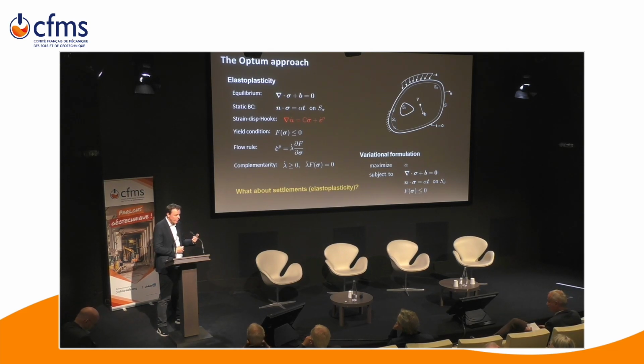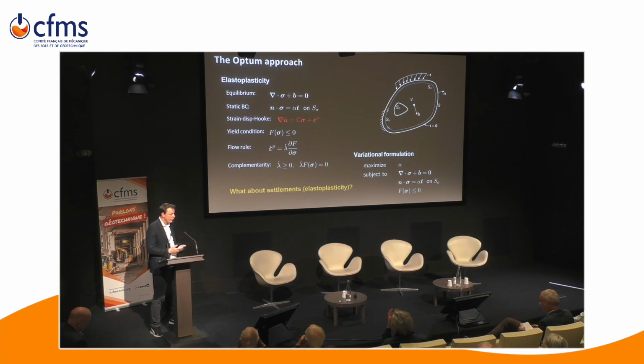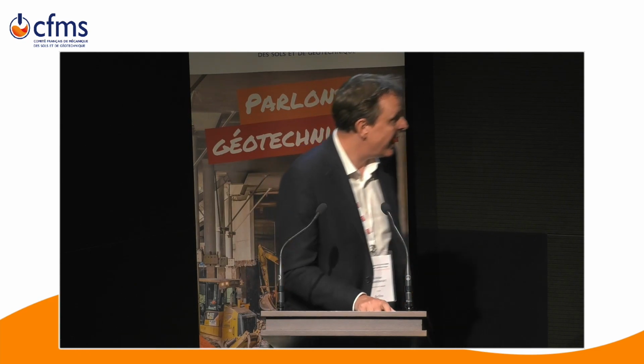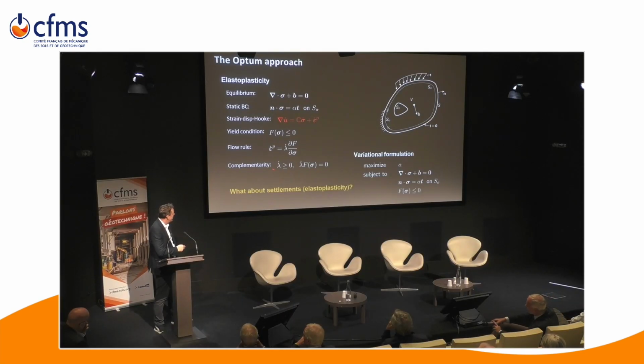I would like to say, though, that for problems that are strongly constrained, the question is whether you can trust anything, really. Because if you do an elastoplastic analysis and you have 1 degree of dilation versus 0 degrees of dilation, you might see a huge difference. So these are problems that in a certain sense are somewhat ill-posed. When it comes to limit analysis, the basic upper and lower bound theorems of limit analysis, there's no getting around the associated flow rule. That's something you just have to live with.